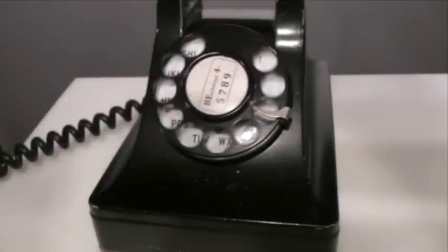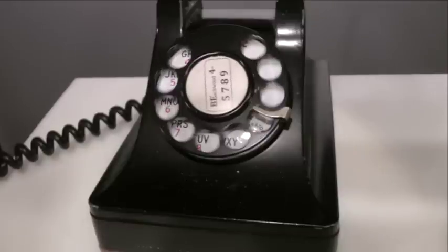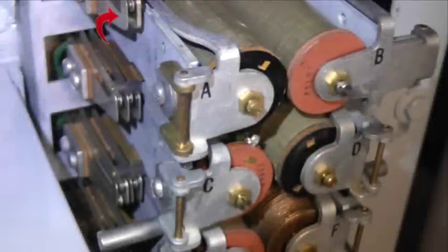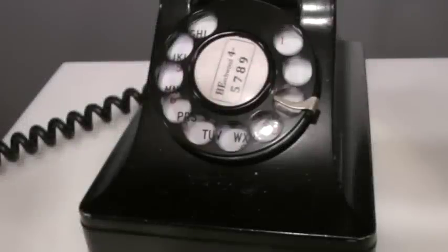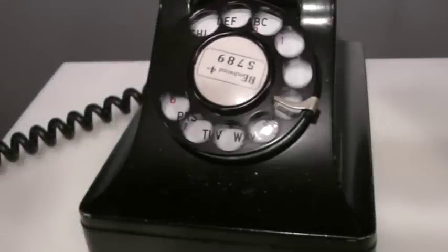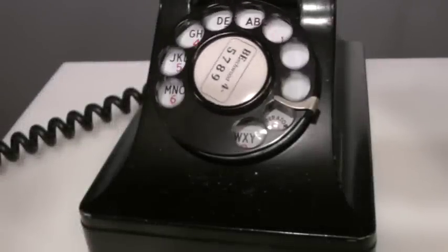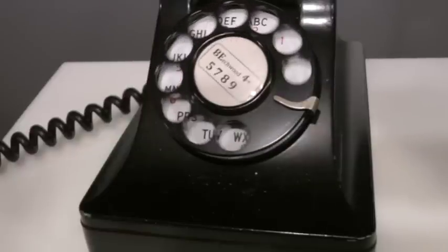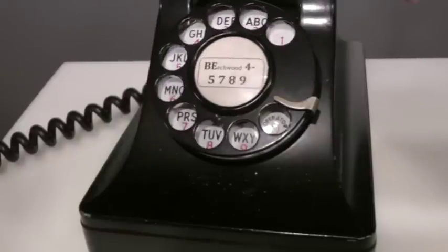As the dial continues to return, it recloses the loop during the last part of the second pulse. The closed loop reoperates the A relay. The vertical armature releases and its attached pawl disengages from the vertical ratchet. As the dial continues to return, for each remaining dial pulse of the tens digit, the A relay releases, the vertical armature and pawl operate, the shaft and its apparatus rise by one step, then the A relay operates and the vertical armature and pawl release.